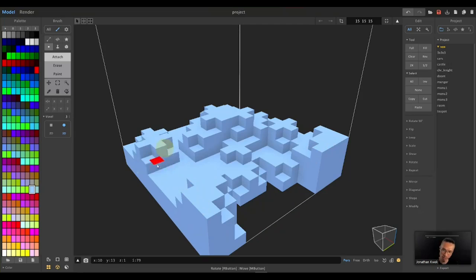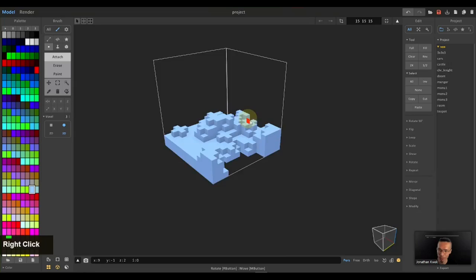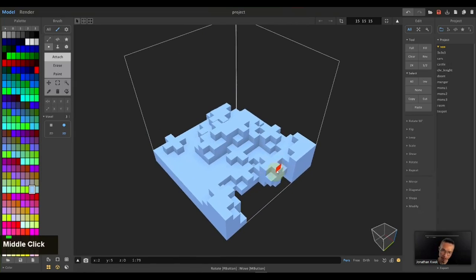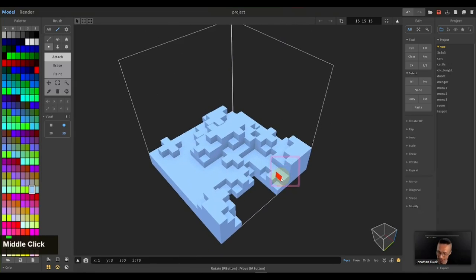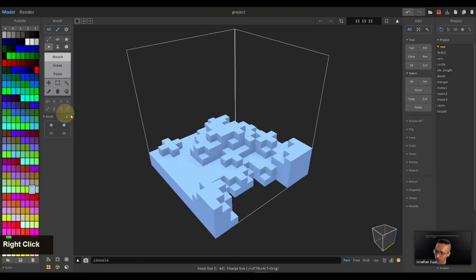So this looks a little bit like a canyon with a little valley here. So very cool. Okay. Then the next thing that you want to play with is to perhaps paint this object. So you can go over to the paint tool over here, and then you can pick one of the colors over here. Now this palette here is quite important, because this whole palette here will essentially become your texture bitmap later on.